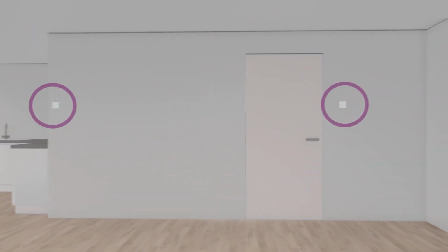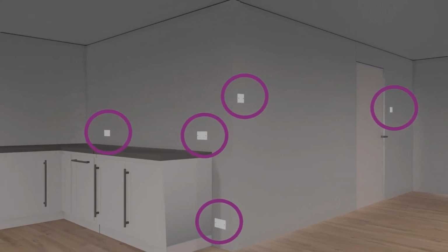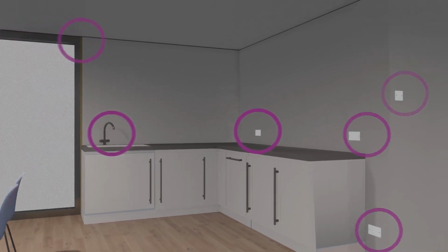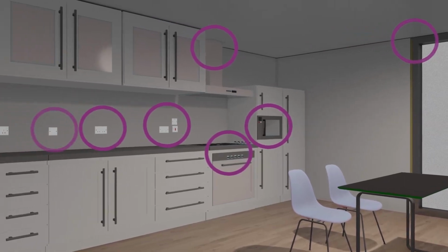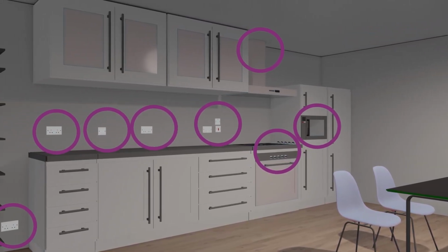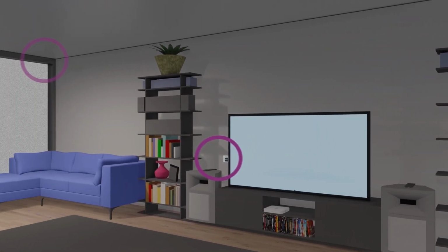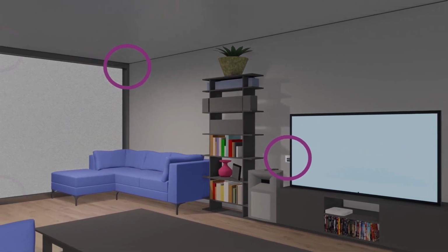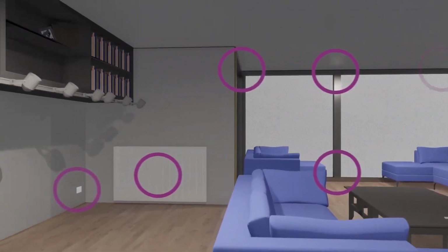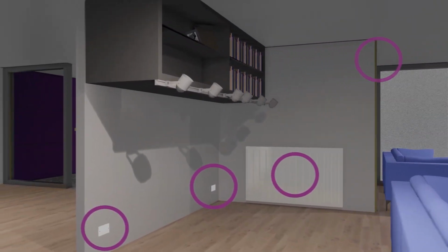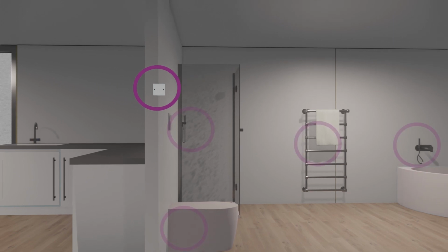As we can see here, if we keep the air barrier internal, that means a lot of tape and mastic required to seal all the switches, sockets, pipework and other services that modern buildings require. A lot of this sealing can be done off-site, but it still takes a lot of time to do correctly, and further care is required to ensure the seals are not broken or damaged during transportation and assembly. Even small punctures, broken or misaligned seals or loose tapes can significantly increase the air leakage rate when tested, leading to expensive and difficult remediation measures to meet regulation requirements.